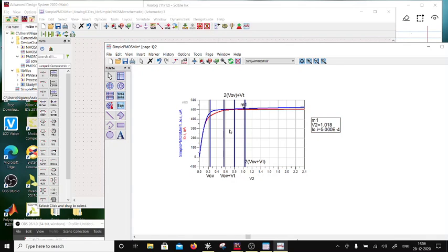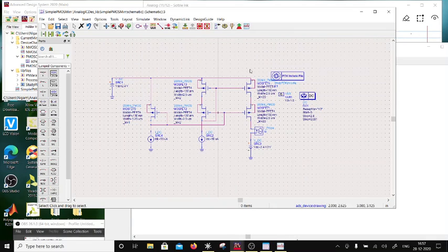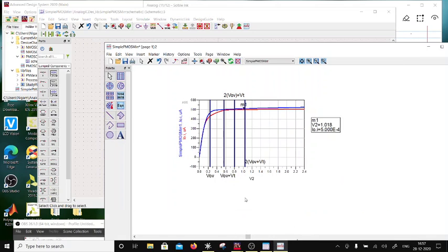okay, what you have done is you have achieved the same thing. So what is the net voltage required over here is V overdrive, and voltage over here is V overdrive again. So we require basically twice of V overdrive plus Vt. So that would be sufficient to make the output current to be 500 or 1:10 ratio. So let's see where you get 1:10 ratio. Okay, so almost here, almost as good as your simple PMOS current mirror.